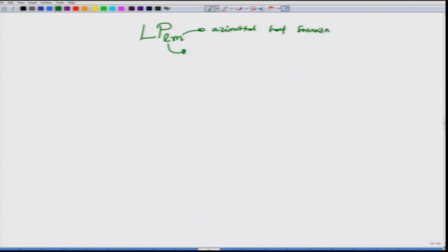Okay. So, these can actually be postulated first, that is what Gloge did. He assumed that the fields could be entirely along Ey, okay, but he also said that this Ey, which is still a function of r and phi, no problem about that, would follow something like this. It would be of different orders L now. Okay. So, you have J_L again with some kappa r inside the core, right. Outside the core, of course, you will have K_L of gamma r.